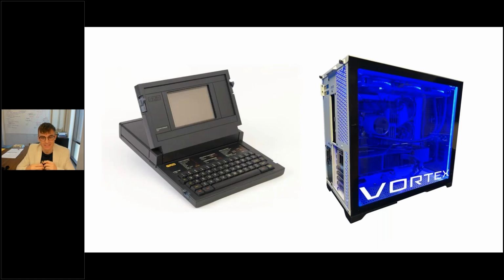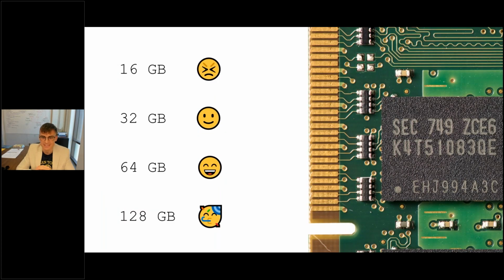After you collect data with a scanner, you will be processing that data. Do not try to scrape by with minimum computing specs. Eventually, you'll take on a job that makes you run out of RAM, makes you run out of hard drive space, and it'll be a headache. 32 gigs is the consensus for a minimum RAM spec. Anything less than that and your software will crash. Get a massive solid state drive so that you can store data and access it quickly.